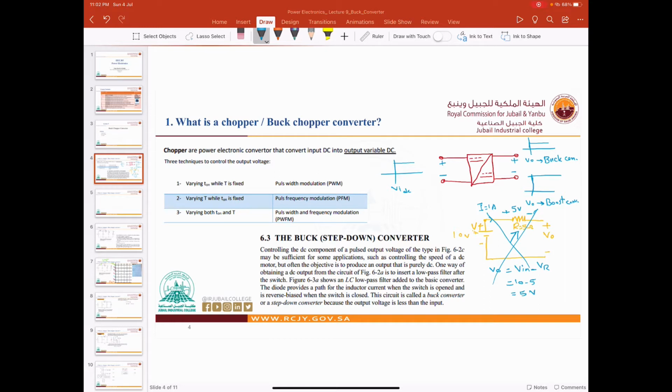Remember, in the lab we have taken, we are using switches in order to switch on and off, and we are controlling the on time and the off time of the switches. Then we can control the output voltage, right? Now this is the best way, and the losses there will be less than here, of course. So the efficiency there may be 95% for the buck, 85% for the boost. And this is fine. But here we have 50% efficiency. So this is very huge losses here.